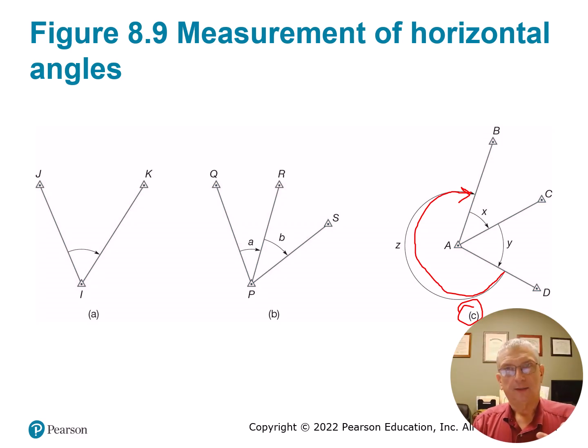So that's one easy way to say, once you've turned the angle twice, the true angle is the double of it, or half of that. That's the average. So that's a little old trick. You've already doubled it, so to take the average, all you do is split it. The more common way is to invert the scope, and that 30, you then just plunge the scope.